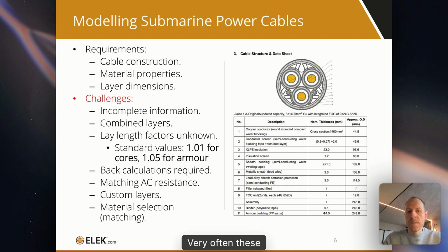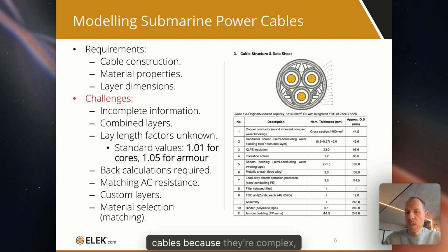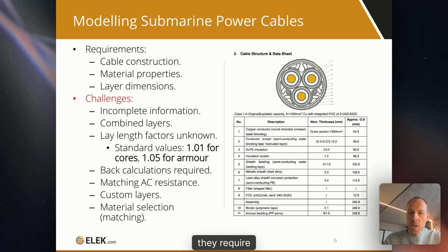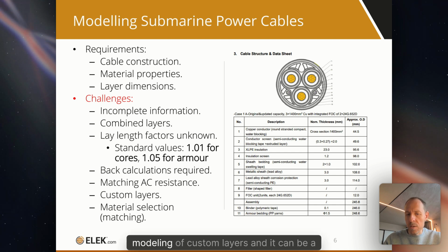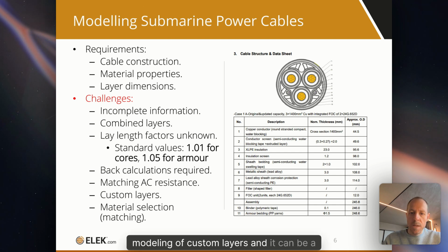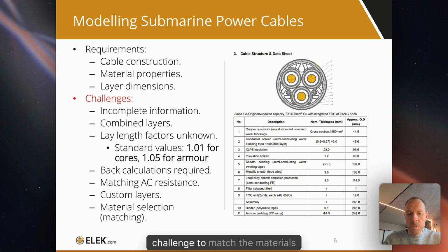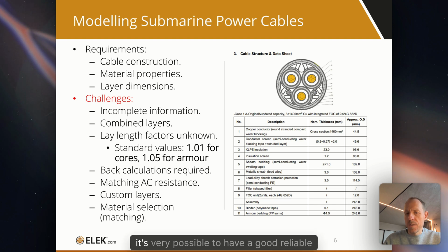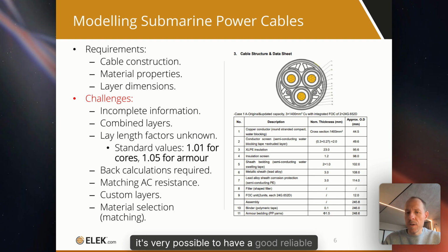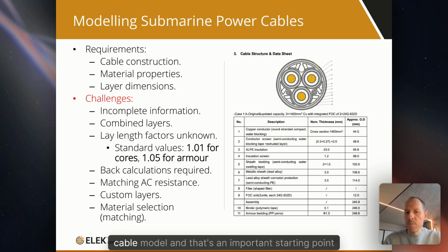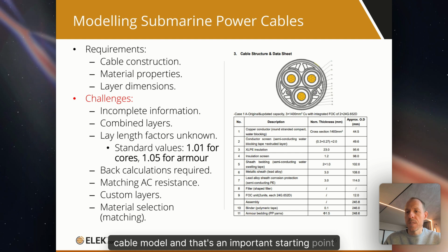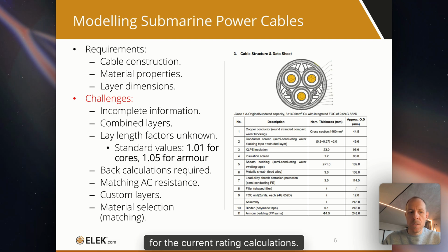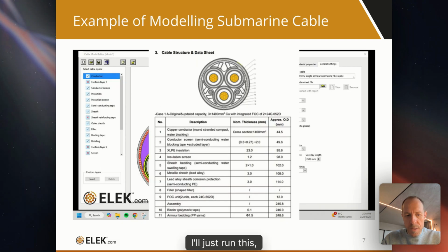Very often these cables, because they're complex, require modeling of custom layers, and it can be a challenge to match the materials according to the data sheet. But it's very possible to have a good, reliable cable model, and that's an important starting point for the current rating calculations. I'll just run this.